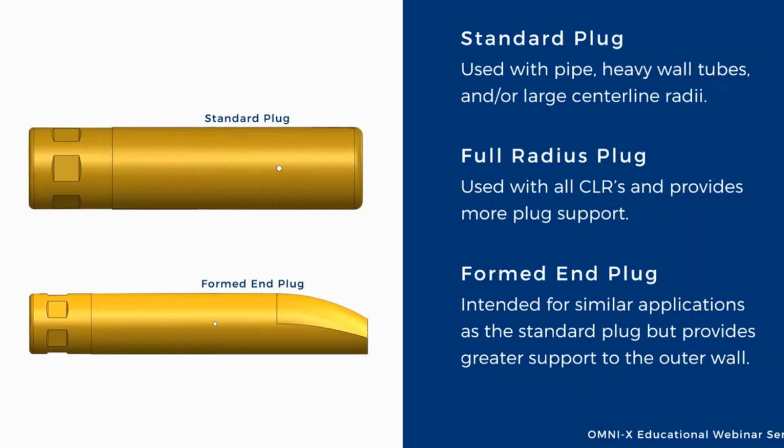And since the mandrel stays stationary at tangent, which is this point right here, and your clamp and bend head rotate around and this stays stationary, the forming always stays at tangent. For more complex plug mandrel applications, you need some additional support beyond the tangent area where the forming occurs. This support can be provided in either a universal radius or a specific radius to your application.